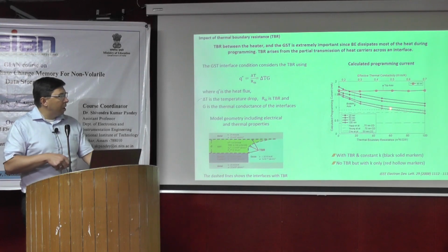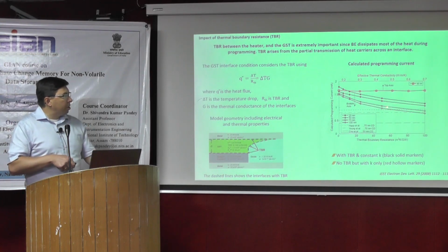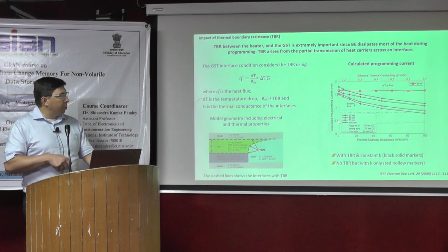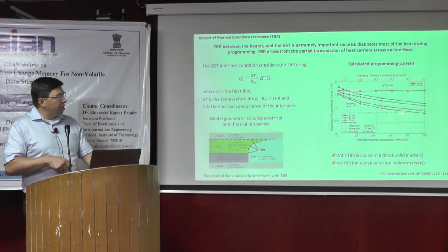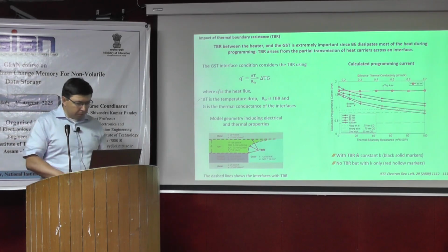The programming current also depends on the thickness of the GST layers: for larger thicknesses, less current is needed for melting than for thin films.